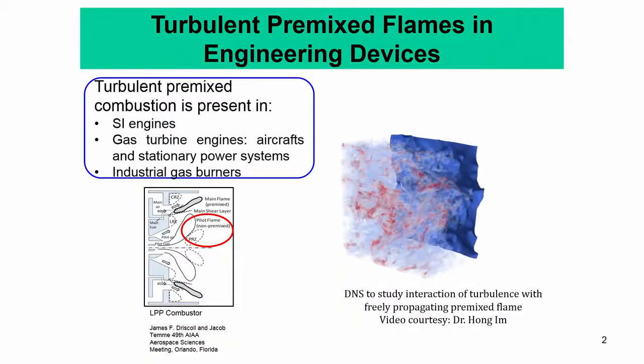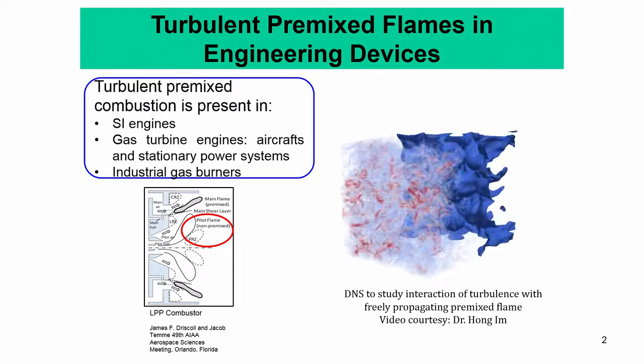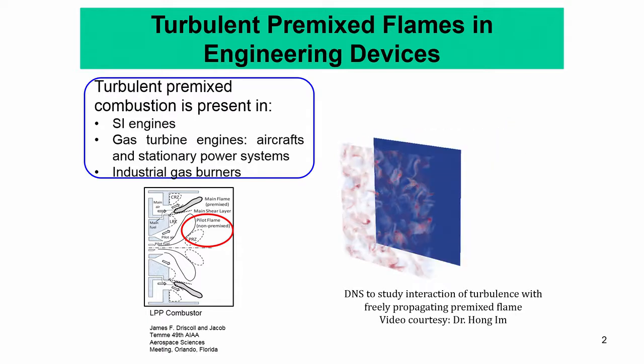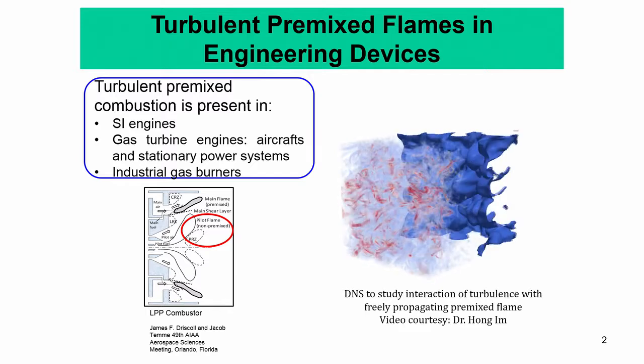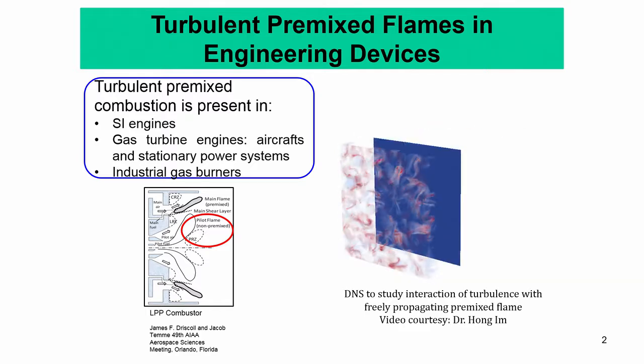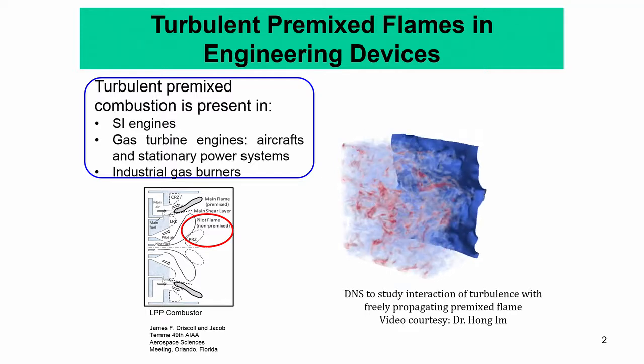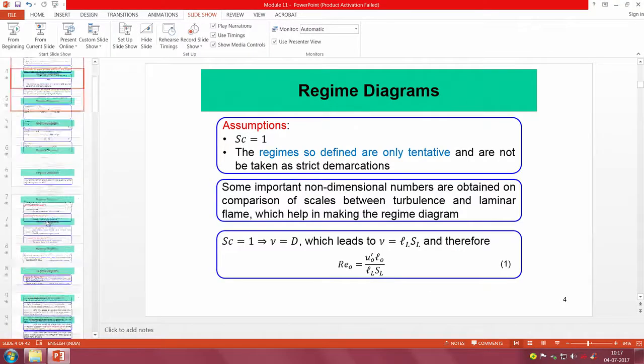Anyway, now we were proceeding to develop the models that can describe the propagation of the turbulent flame. As you see from the video that we saw at the beginning, we can understand turbulence-flame interaction by considering what happens on different isosurfaces inside the flame, isosurfaces of temperature. Then the task is to describe the evolution of these isosurfaces under the impact of turbulence, from large-scale turbulence to small-scale turbulence. And for that we went on to describe the G equation.